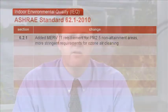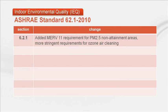Now let's step back and discuss the 2010 version of ASHRAE 62.1. There were lots of changes between the 2007 and 2010 versions, but I'll try to summarize the most significant changes that might affect a typical LEED project. First is a new requirement for air cleaning of fine particles. In those areas where the outdoor concentration of particulate matter, 2.5 microns and smaller, exceeds the national standard, Standard 62 now requires the use of a MERV 11 filter. And for those areas that exceed the average daily maximum level for ozone, an ozone air cleaner is now required.